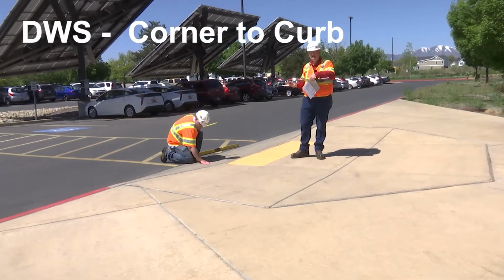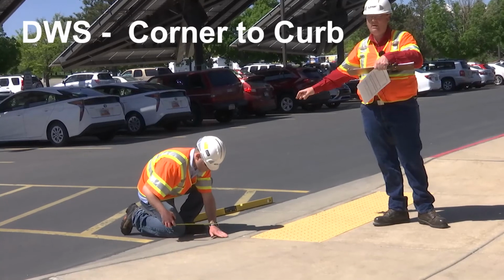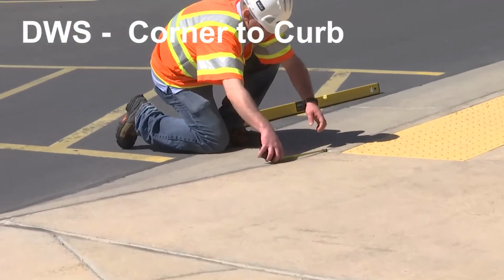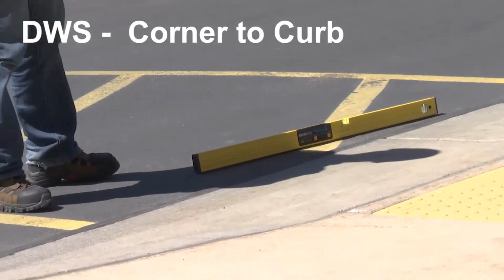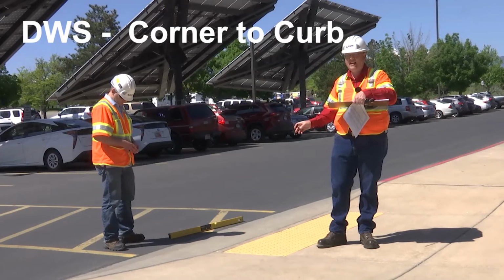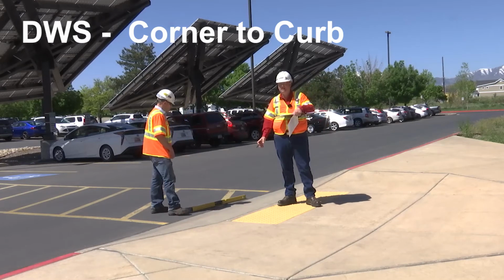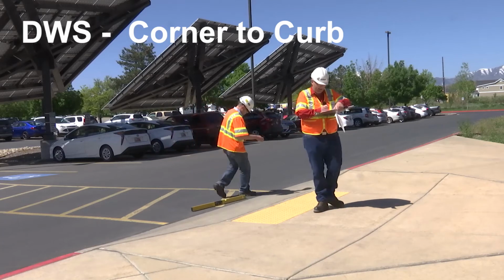We should move our detectable warning surface a couple inches, or preferably all the way to the base of the curb cut. Here we are about 1.5 inches from the base of the curb cut. And here we're 1.5 inches away from the curb cut from where the detectable warning surface starts. For that aspect, we're okay. We're just out of compliance where the detectable warning surface is in relation to where the top back of curb is. We just need to move that in a couple of inches to be within compliance.